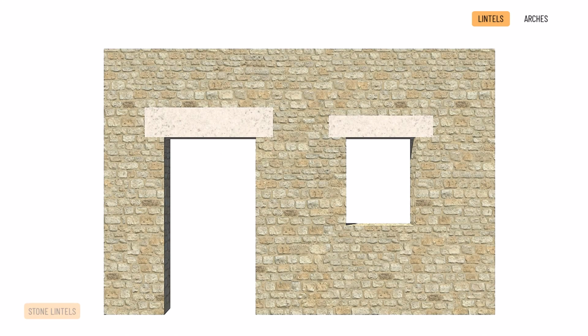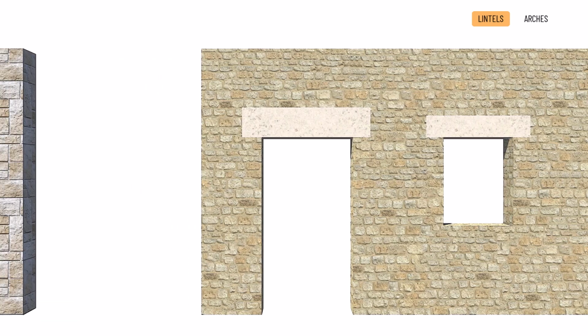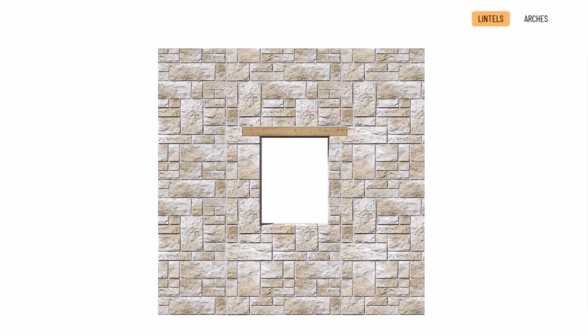Stone lintels. The tensile strength of stone is extremely low, so it is not economical as a bent structure. It means that spans of greater width can only be achieved with an exceptionally high structural height, which is not an economical solution.